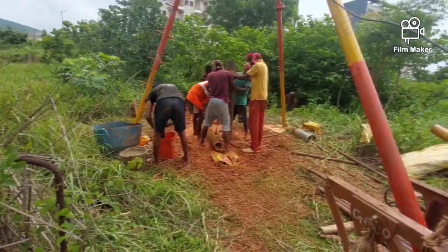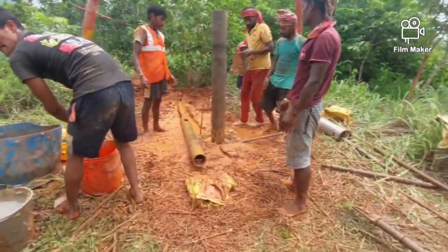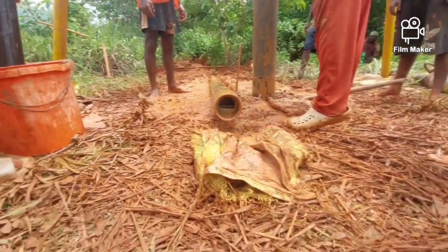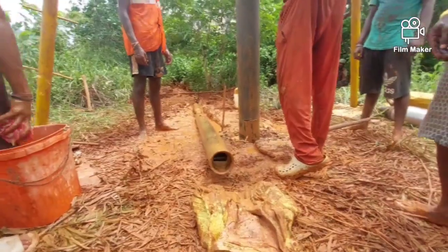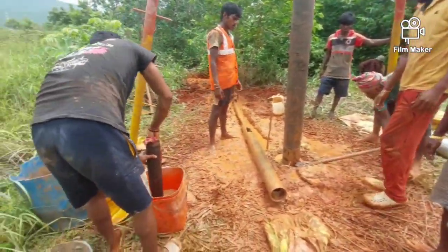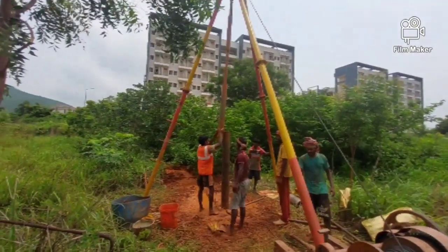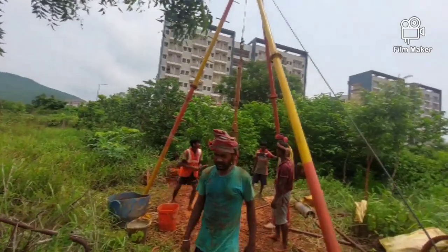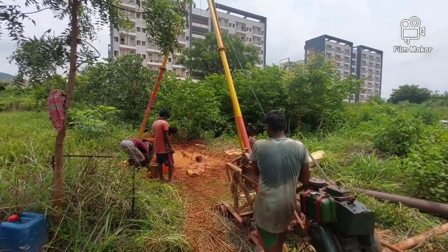We can see that at first, through the Shelby tube or another core cutter, which is attached with the valve here, to reach the desired depth, after every 1.5 meter depth. So one core cutter or Shelby tube is fixed into the borehole, and then cutting up to the required depth.